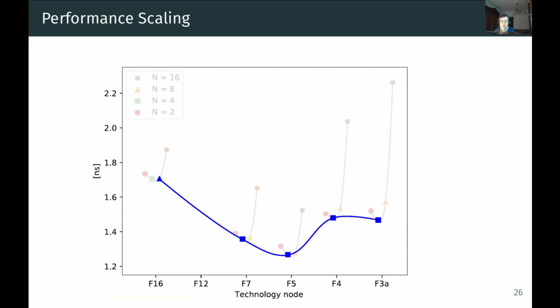What is also interesting to see is how the evolution of the best performing architecture actually proceeds. And here we can see something that is maybe a little bit worrying: not only might the performance gains be lost as technologies progress, but the performance of the more scaled technology nodes might actually become inferior to the performance of one of the older technology nodes. In this case, the 4nm and the 3nm node perform worse not only than the 5nm node, but even the 7nm node, 2 generations before.